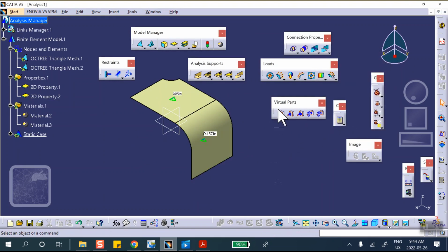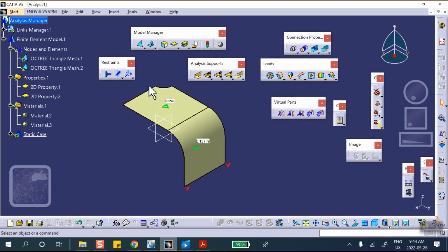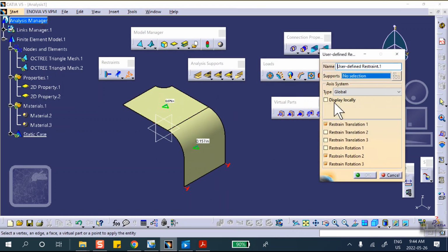Okay. The bottom is clamped. This bottom is clamped. Okay. These 2 edges. Let's see which 2 edges. Let's see for a second. This edge and that edge and that edge, all 3 of them actually, all 3 of them lie in the YZ plane. They don't move in X, rotations exactly opposite.